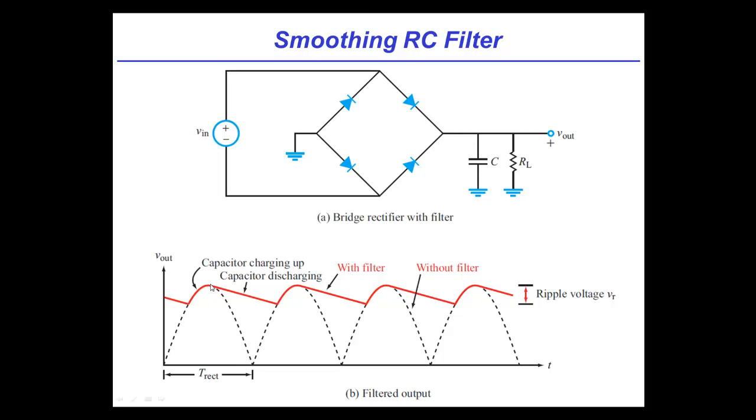That's exactly right. And so the bigger the C, you might even be able to, this is a little exaggerated for a realistic one, you might come down and just barely discharge, and then of course the thing flips again and it starts to charge it up just a little bit and discharge. So there's a lot of charge always on this cap. So in real power supplies, you'll often find that the value of that cap that's used for filtering is several thousand microfarads. So in the millifarad range is certainly common.